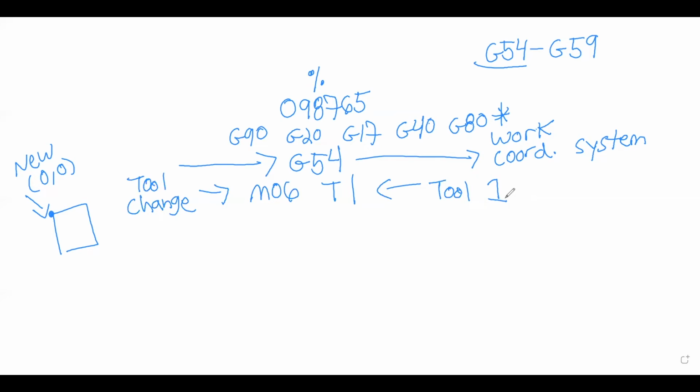Now, things are starting to come together with G codes in our safety line, our work coordinate system, and calling up a tool change. Once a specific tool is in the spindle, we will move to location. This is going to be a G00. This is a rapid movement, a non-cutting movement used for a quick position to a location for cutting or for clearance.